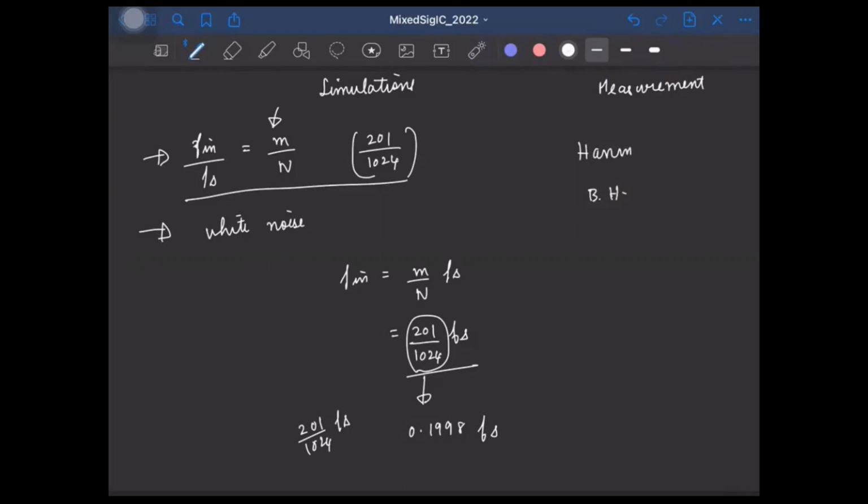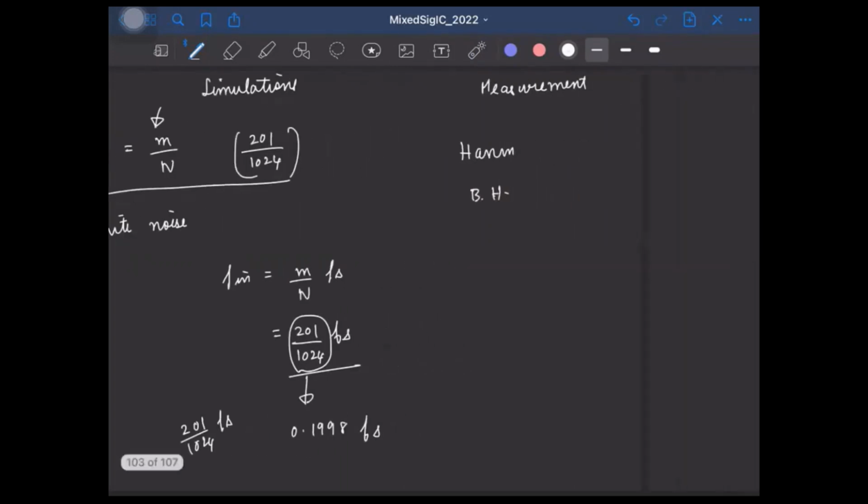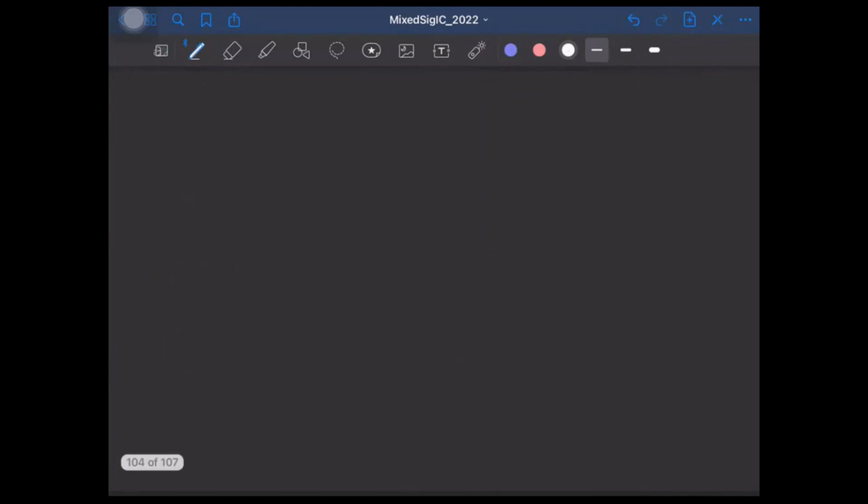Okay. So one last thing regarding windows. Till this point, we have been dealing with cases where the noise power spectral density was flat. That's why even without windowing, it seemed fine. We saw with white noise, even though there were jumps when you have the periodic repetition, the flat noise introduced by these jumps might be very small in practice compared to the actual power spectral density of the white noise, and so they might not be of any consequence.